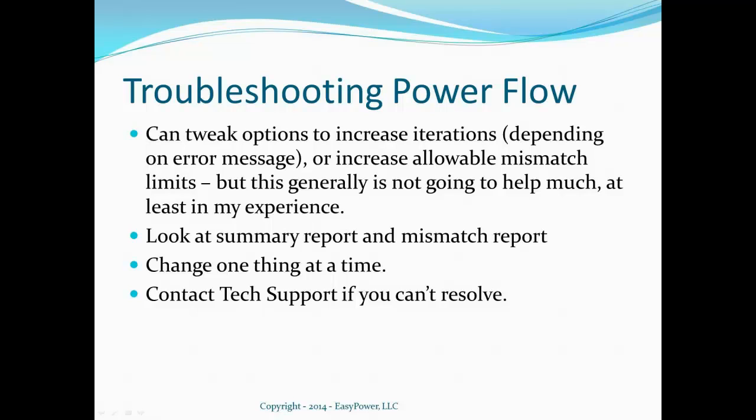We have a transformer that only supplies power to a single motor. Can we use LTC to fix the motor starting voltage? Probably no, because the LTC is too slow. It takes a fixed amount of time for it to change taps and respond to the low voltage conditions, so it's going to be too slow, and that's not going to help you at all for motor starting. One thing you could do is manually raise the voltage before you start the motor, and that would be kind of a nuisance. So in general, the automatic LTC is not really going to help you for motor starting.